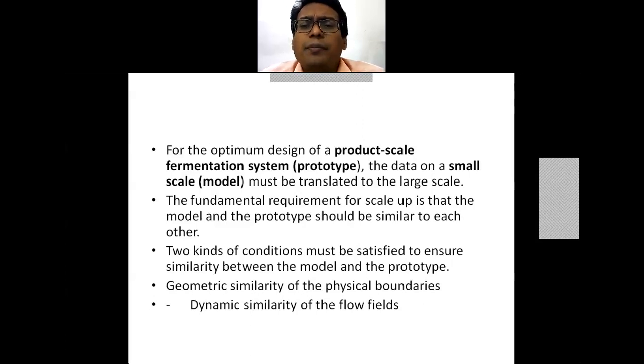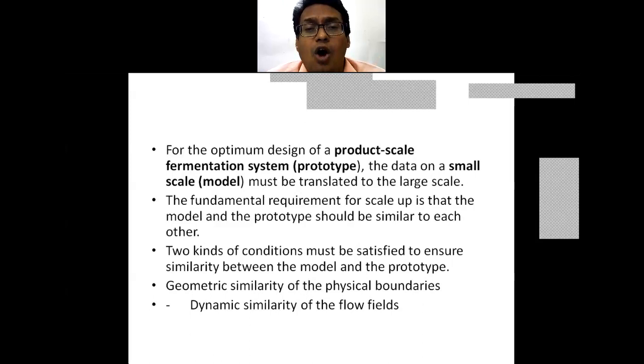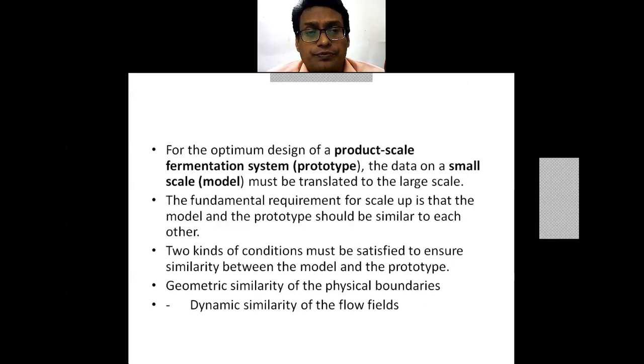So for the optimum design, whatever results I have obtained in the laboratory should be reproducible on the production scale. So one has to correlate the different parameters in terms of the geometric similarity and the dynamic similarity, which will provide me the resultant output similar to that of the laboratory scale products.